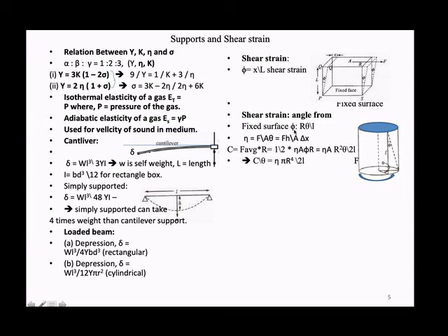So that is how the shearing strain comes up: r theta by L. This is r theta and this is L. So here the strain is phi. Phi is unitless, in radians or degrees. Now what is the rigidity modulus? Stress by strain. Stress is F by A, strain is phi. So F by A into delta X by H. This is assumed as delta X.